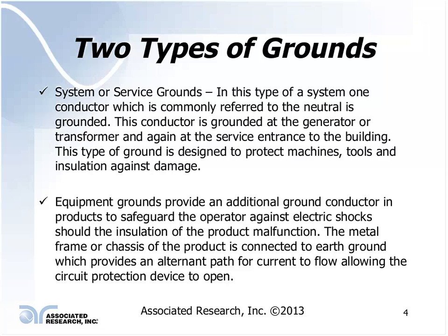Because all of our power systems are essentially referenced to Earth, the current tries to get back to that source. One way of protecting individuals that are handling products is to ground the enclosure of that product so it is at that Earth reference.